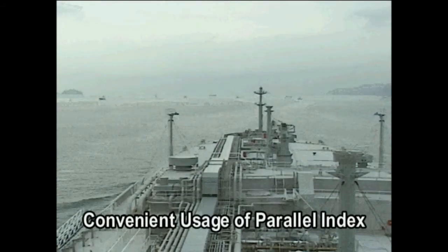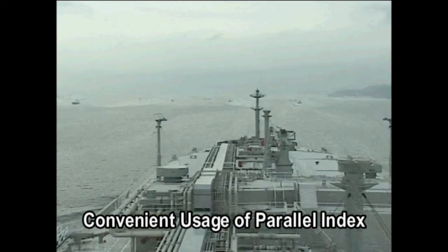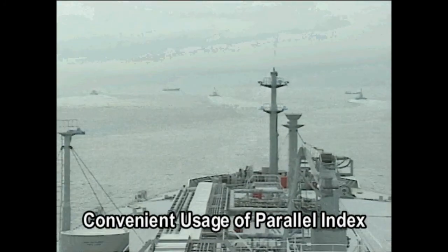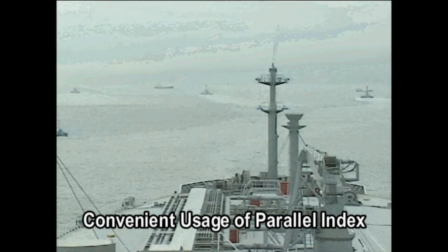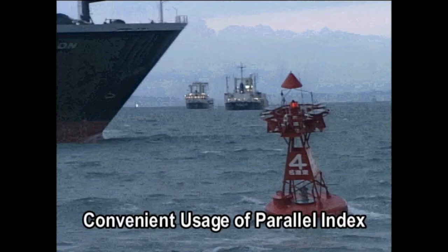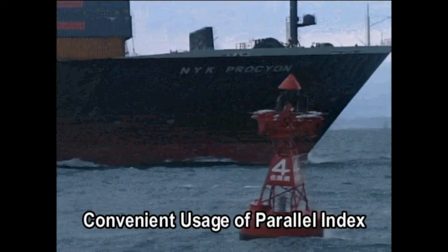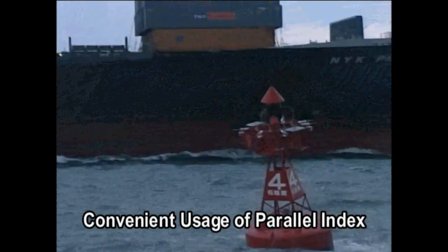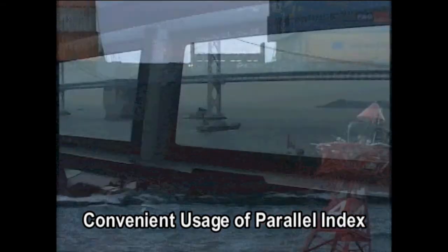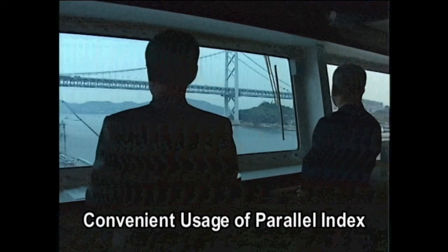If owned ship is drifting off the set course, it's easy to determine the influence of sea currents and winds by placing a cursor line parallel to the heading line of owned ship at a safe distance from a conspicuous target, like a steep headland, the tip of a breakwater, an isolated rock or islet. Use of a parallel index line is also effective for maintaining a safe distance from the coastline when owned ship is coasting.